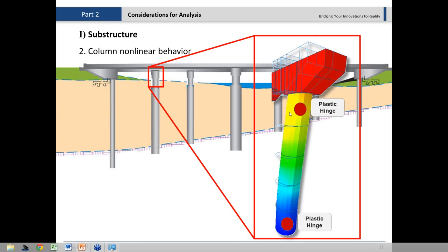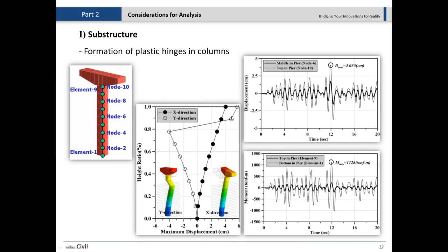All right, so what we can do is find out the plastic hinge property, which is a function of the material that I use, for example the concrete and the rebars that you use there. The combination of those leads to finding the plastic hinge behavior. That's pretty important, because the failure of this structure would probably be considered when the first plastic hinge forms there. So it's going to be the ultimate, or the failure, of that structure.